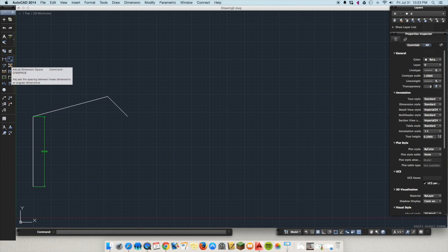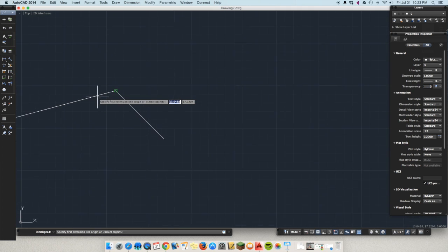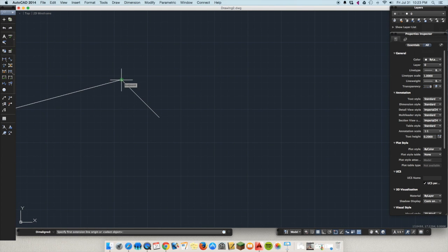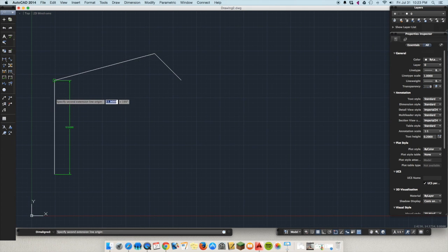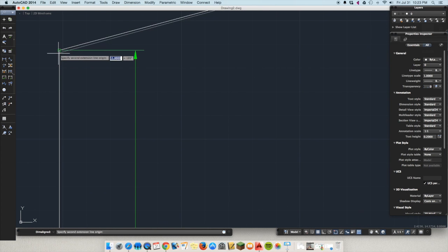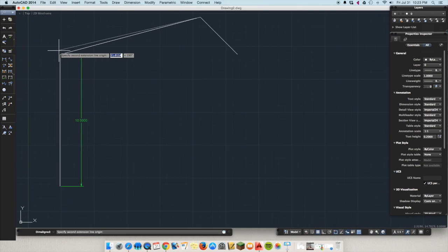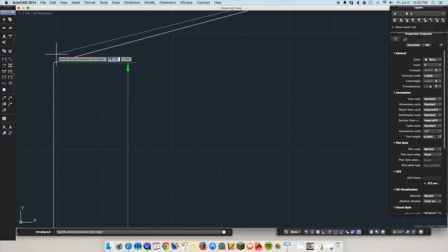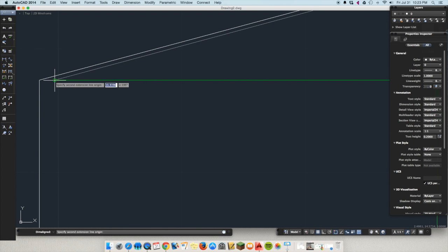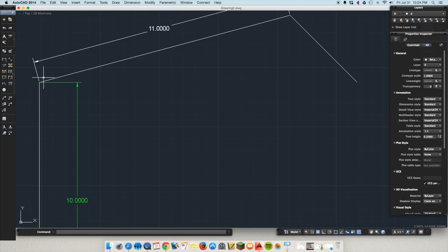And then the next one, you would continue. The only trick with doing multiple ones that overlap, let me show you, is I'm going to click on this side, and I'm going to zoom way in. You'll want to zoom way in when you do this. You can accidentally, let's see, this was an 11-inch line, but I could make it look like it was something less than that if I accidentally snapped onto the dimension line itself. Do you see how that's letting me snap onto either place? So just be careful that you're actually snapping onto the line end and not the dimension end.